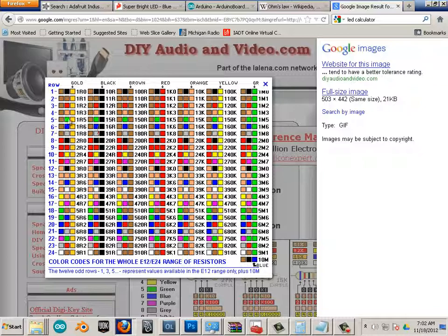So this way, less resistance, higher current. All of a sudden, lots of current gets to the LED and fries it out. This is the minimum that is required. So we got to have that. And then what I had was this one over here, so it made the LED a little bit more dim. As I go out more and more, it gets dimmer and dimmer and dimmer.